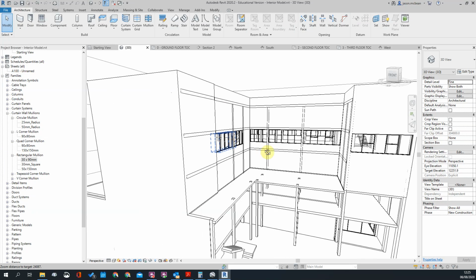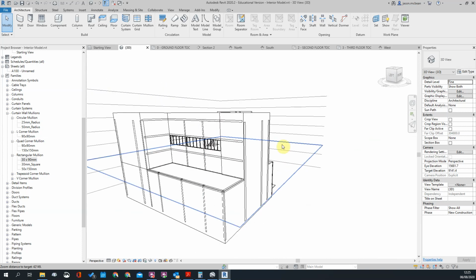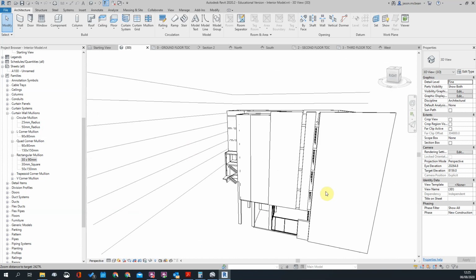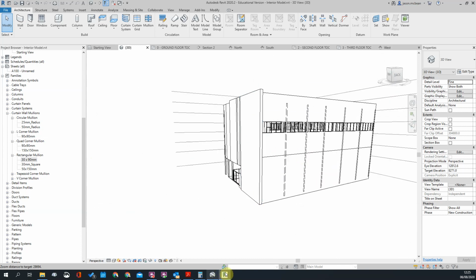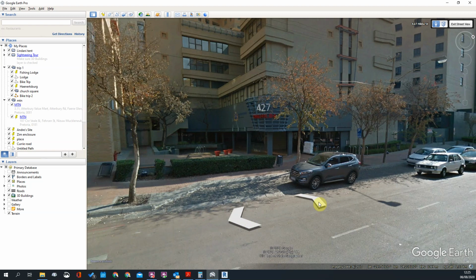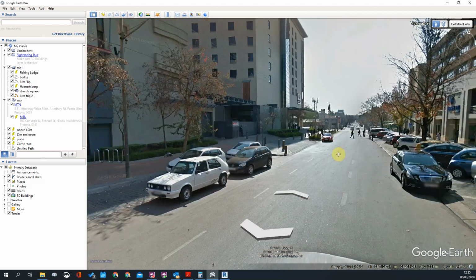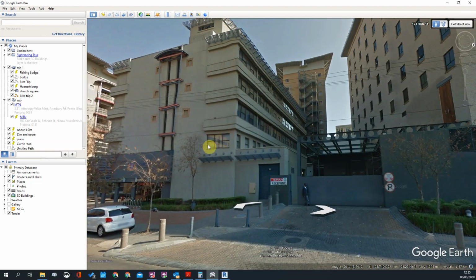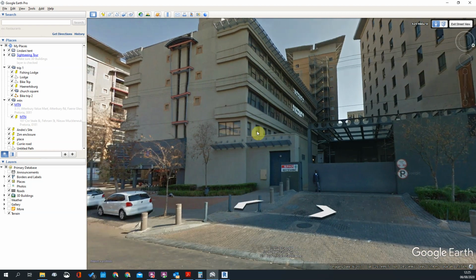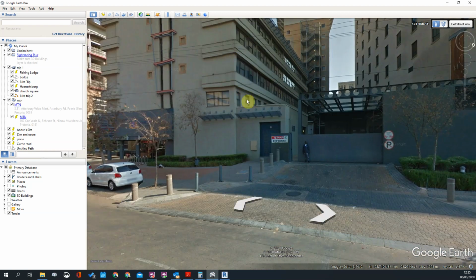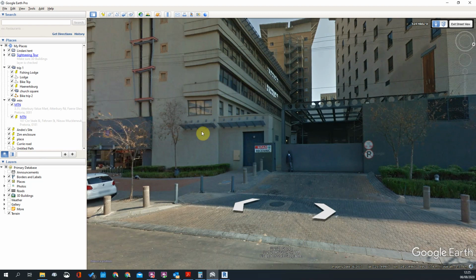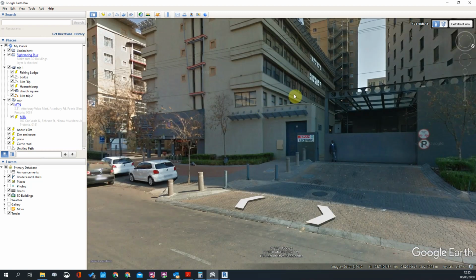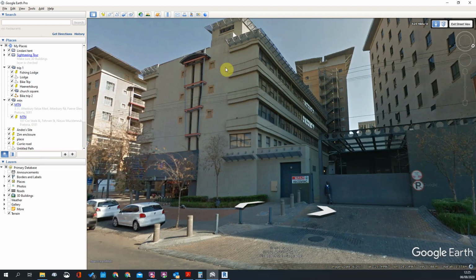Okay, and then in our shafts, we've got our windows appearing, and I suppose these windows will go all the way around. However, we do have a situation where the windows, if I go to Street View again, but what is nice is I've got a family that I can use already that I can adjust. So, let's just go over here. We look at the building. Here we've got, we could use those, we can use curtain walls again to do the same thing. Or we can use an actual window family for that. But I think I'm going to use a curtain wall system for all of those as well. That's a different window that we can have a look at as well, make separate.